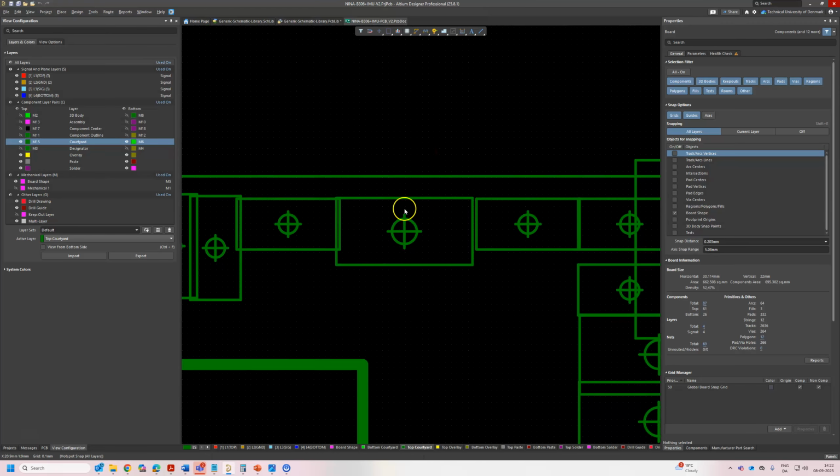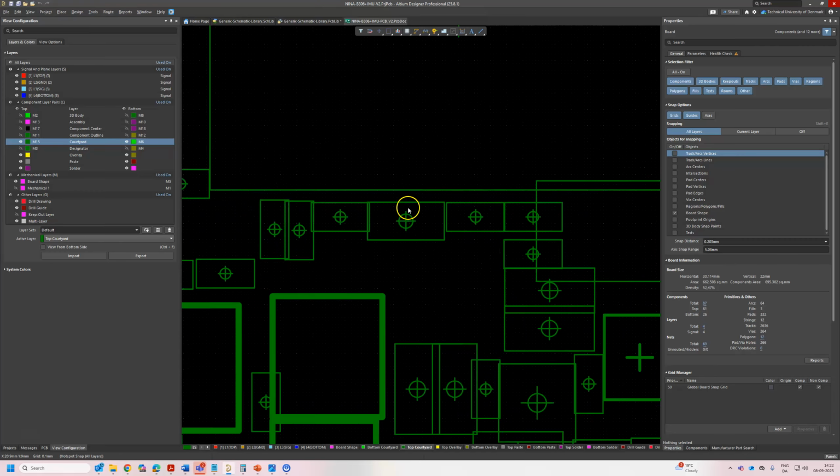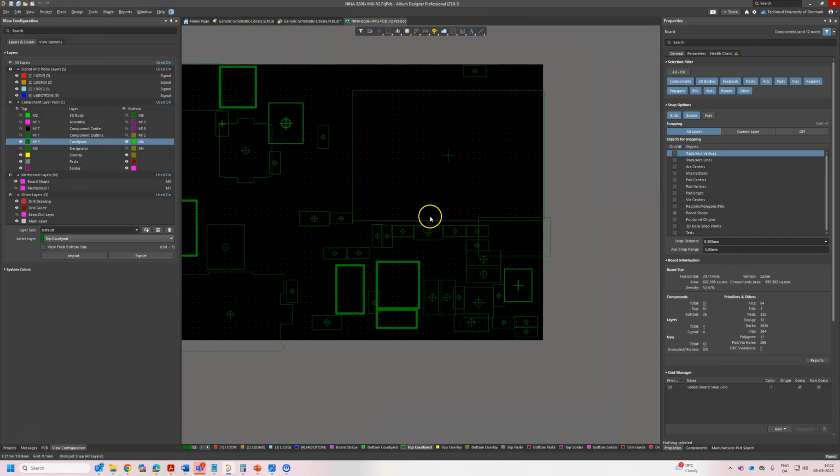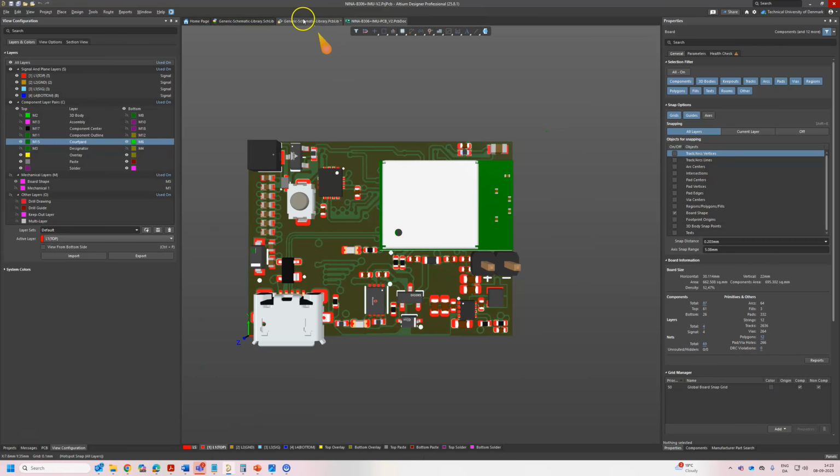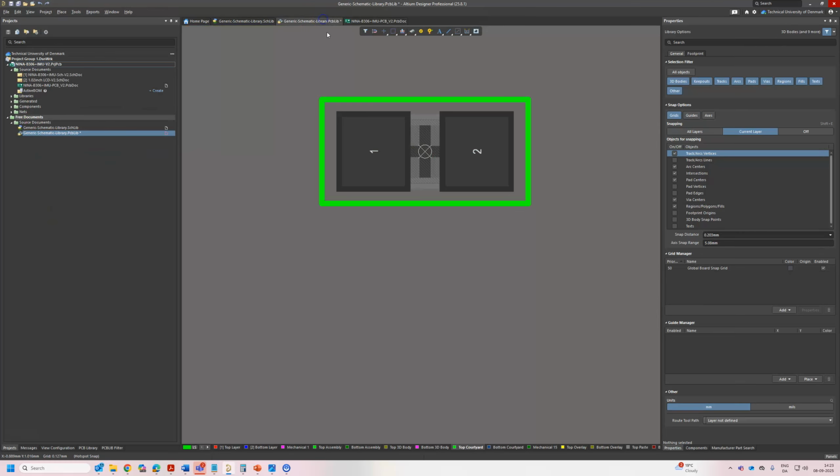it will actually show me that I should not go any closer. So I can go a little bit closer here, but I have to respect this line and not go above it. So that's when it's really useful, especially if the pads are under the module, which you cannot really see. Let's go back to our PCB here. Shift S to see all layers, and let's save it.